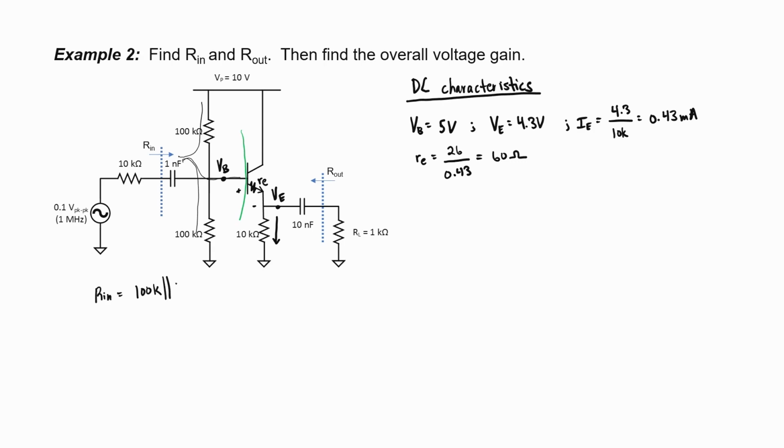We therefore have the two 100 kiloohm branches, and then for the impedance reflected branch, we're going to have emitter resistance r sub e, which is in series with two other resistors, 10 kiloohms and 1 kiloohm, which are in parallel with one another, and all that's going to be multiplied times beta plus 1 since it's reflected. Plugging in an approximation of 100 for beta, this all works out to be about 98 kiloohms. The net input impedance is then 33 kiloohms.